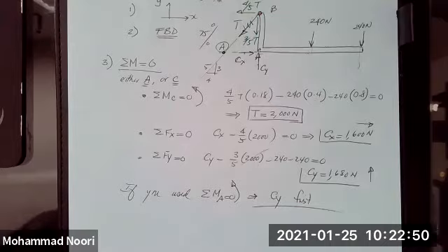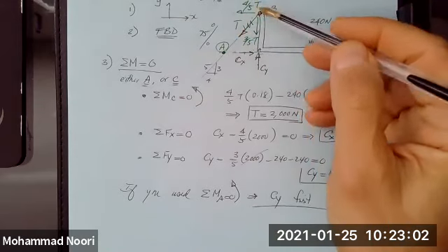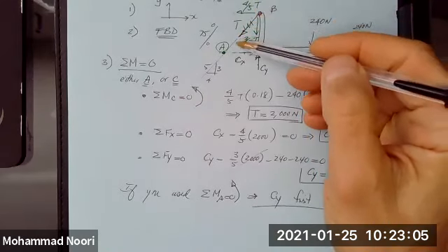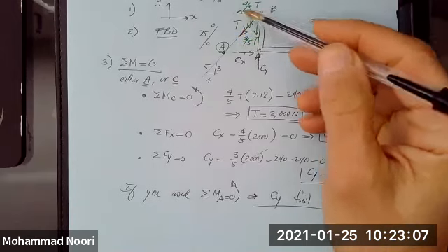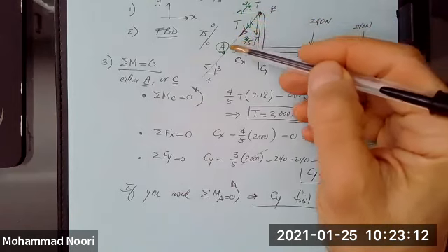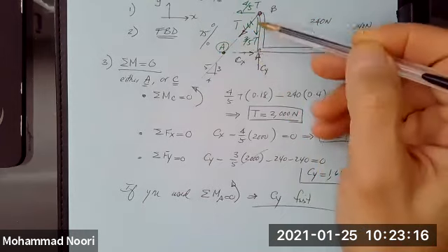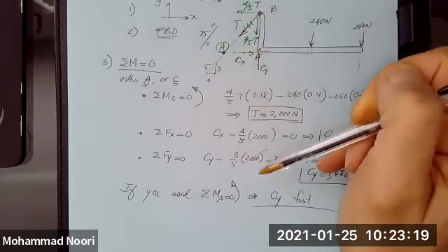If not, if you were to use point A instead of point C, would the horizontal component of T generate a moment about A? Oh, if I used A, what I would do is leave T as is. I won't resolve it into the two components. So I can see that T is going through A and CX goes through A. So I would only have CY as the unknown. You see what I mean?